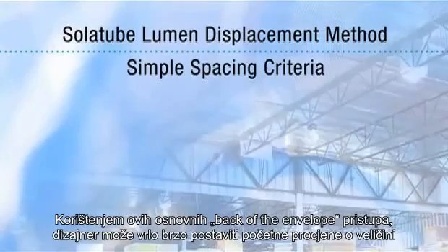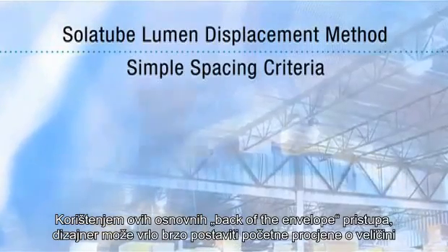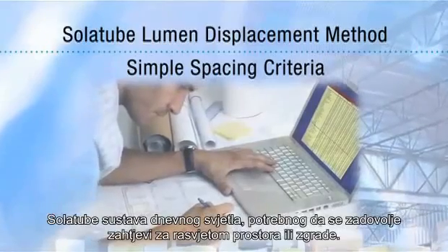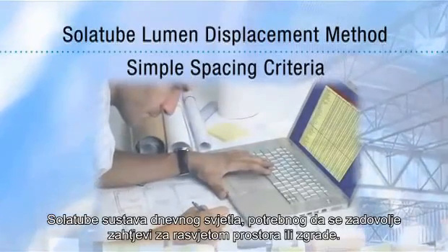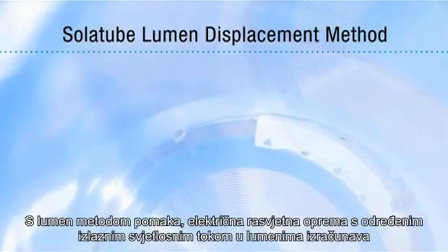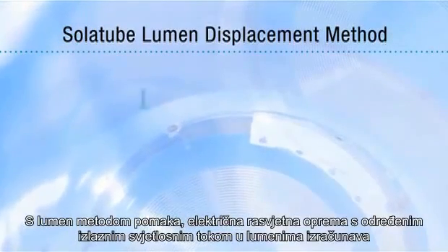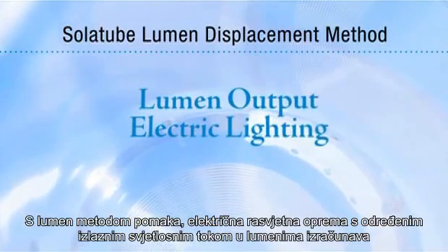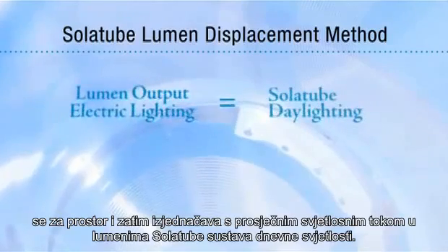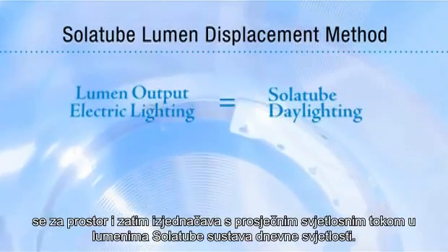Using these basic back-of-the-envelope approaches, a designer can very quickly establish an initial estimate of the quantity of Solatube daylighting systems necessary to meet the lighting requirements of a space or building. With the lumen displacement method, the lumen output of electrical lighting equipment is calculated for a space and then equated to the average lumen output of Solatube daylighting systems.